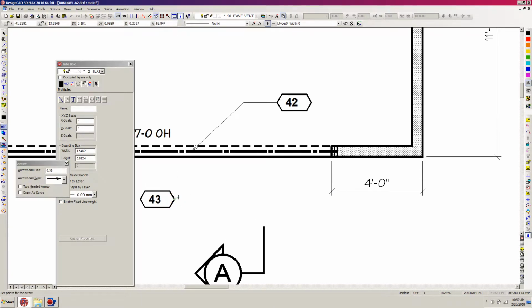Z, and I'm going to hit the arrow command, again greater than. Right click on this portion of the sheet note box, hit H for orthogonal mode, come on down a ways, and now I'm going to set one point by just hitting the left button on my mouse, H to go out of orthogonal mode, and K at the center of these double trimmers. And so there's my arrow pointing to it.